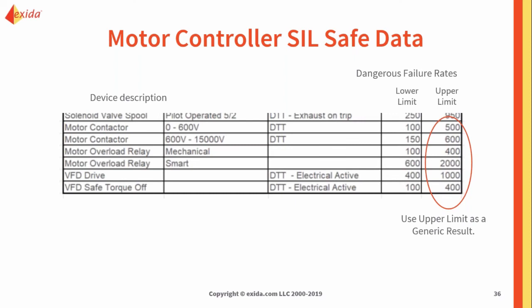However, without knowing everything about the operation and application, you can't use something lower than that, unless you go back and look at failure rates, FMEDAs, or any of that. And that's also an option for you. If you ever have a device and you need failure rates, you can always do an FMEDA analysis for the device. We have had customers do that as well.